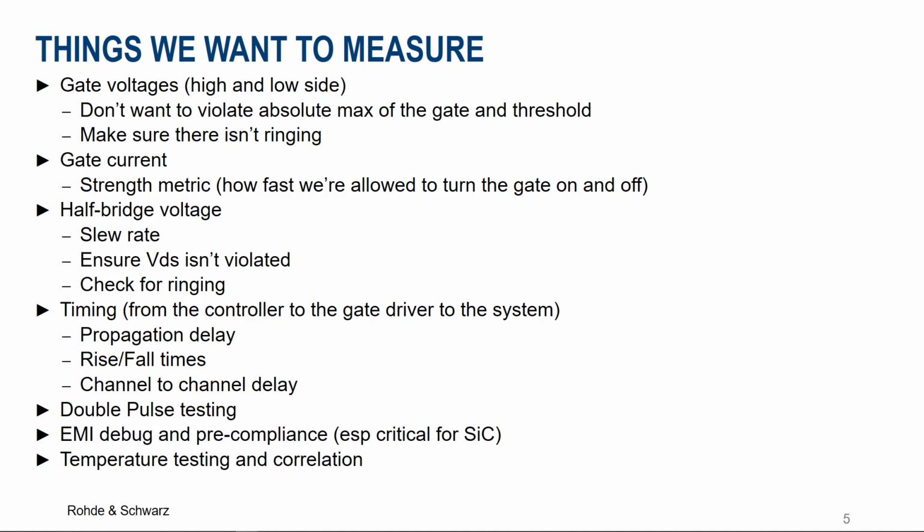Pulse width distortion is the difference between the rising and falling edge delays, and it can cause duty cycle variation within a given drive. A lot of times, pulse width distortion will show up on datasheets because it's easier to report. One description of skew, which I think helps understand it, is it's a variance that acts like jitter. It's also important to ensure the system is robust against noise.